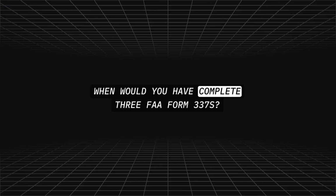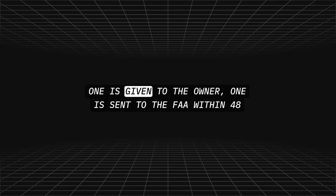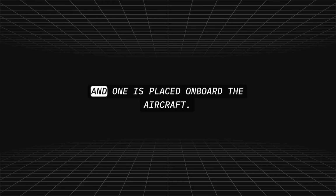When would you have to complete 3 FAA Form 337s? When installing extended range fuel tanks in the baggage or passenger compartment. One is given to the owner, one is sent to the FAA within 48 hours after the aircraft is approved for return to service, and one is placed on board the aircraft.